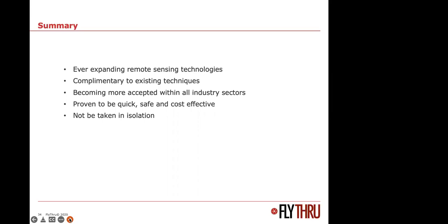The guidelines will be there in any training, tell you who you've got to speak to. Don't try cutting corners. People say you can't fly over Network Rail land, but you can if you're more than 50 meters away. It's a lot easier to speak to them and say, I'm going to be flying here, is that okay? And them saying yes, than it is to cause a problem and trains being stopped, etc. So yes, it can be onerous if you don't know what you're doing. If you've got some experience or you've done the right training, make sure you tick every box that you've been asked to tick prior to flying.